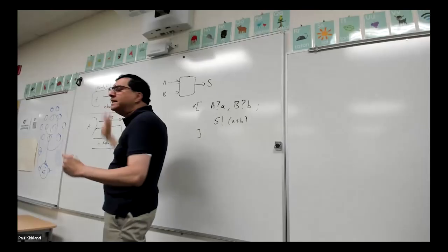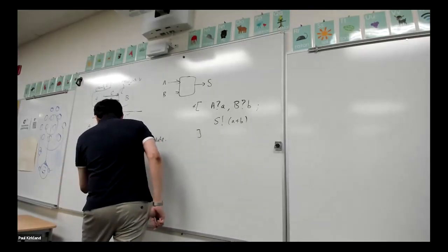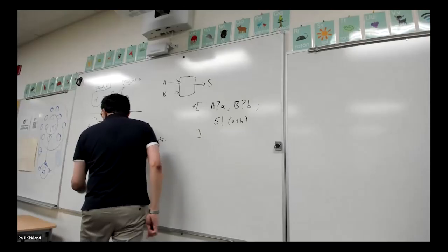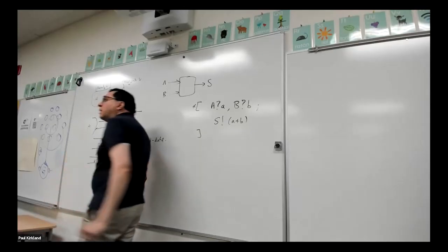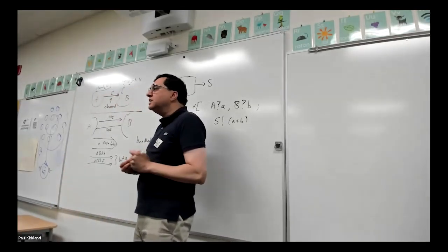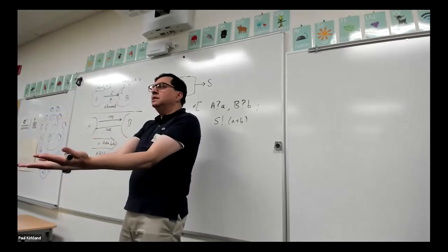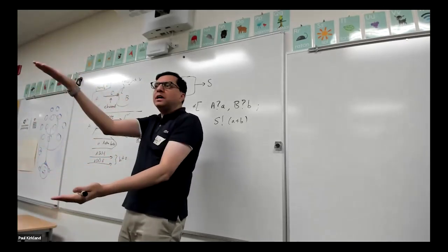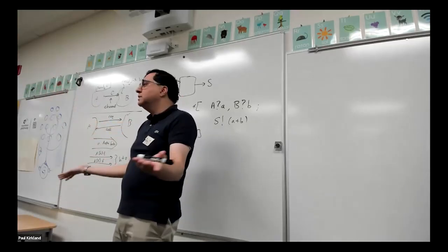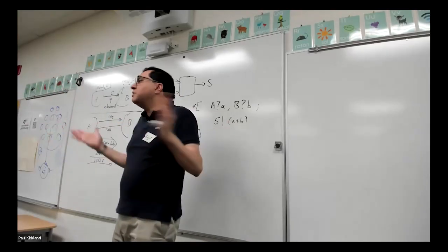And then I don't even need the request. So this is bit 0, D0.T. Two wires for true and false. Initially, I'll just show you how one bit works. Initially, both wires are low. I set the true wire high to say it's a true, and I set the false wire high if it's a false. So at the receiver, it doesn't matter what the delay is, you can tell when the bit is there, and you know what the value is.